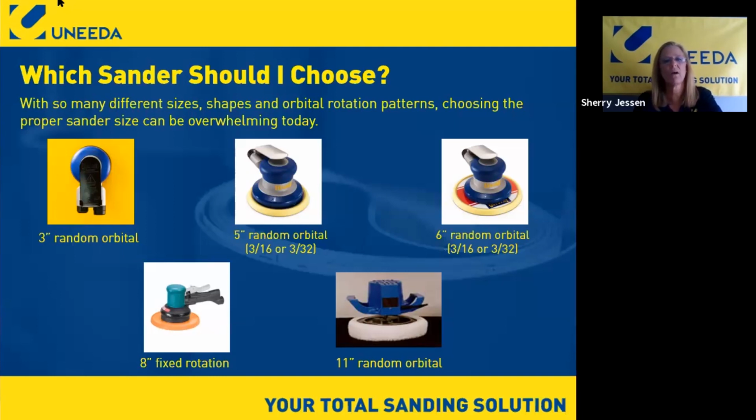Yes, it does. With our sanders, our 5-inch, 6-inch, and our 3-inch are aluminum housing. The reason we chose aluminum housing is that it absorbs vibration a little bit better. When you've got a composite body and you start to sand, especially for somebody sanding 8-10 hours a day, holding that sander, your hand starts to go almost numb.